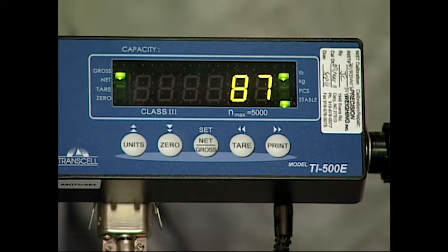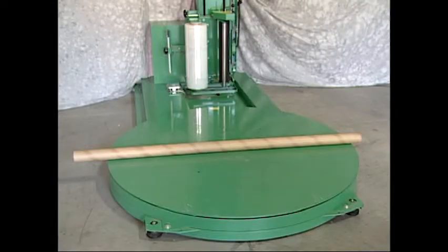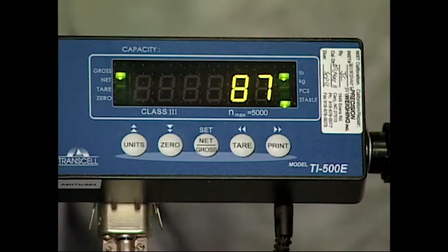If a roll or bolt is weighed, the roll shell or holder is also weighed. If the shell or holder can be removed, it should be weighed by itself. The net weight is determined by subtracting the shell weight from the total weight. The weight per unit area can then be calculated with the following formula.